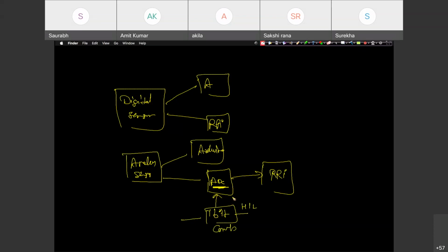If you need more bit resolution, if you want 10-bit resolution, your data should not be converted into just high or low. It should be converted into bits, like 10 zeros till 10 ones, in digital form, right? So if your values are coming in 10-bit resolution, at that time you cannot work with a comparator. You should have ADC circuits.